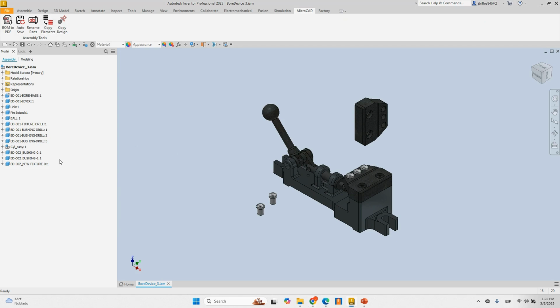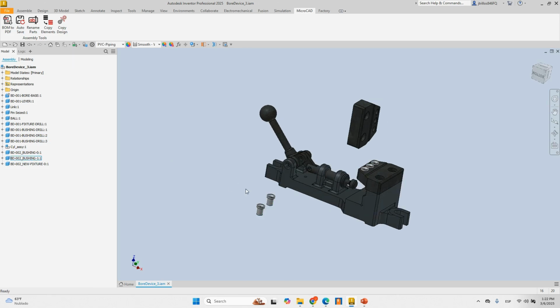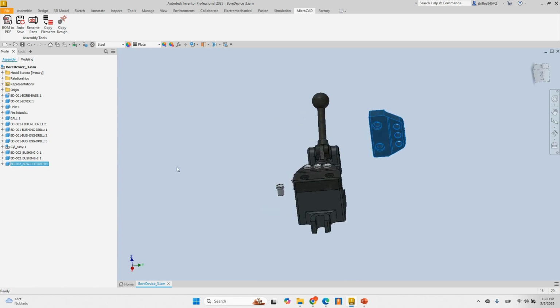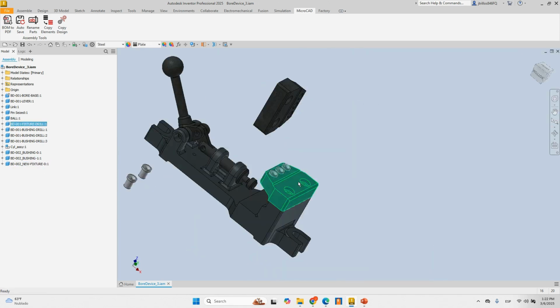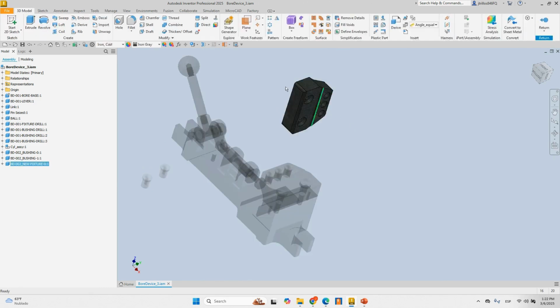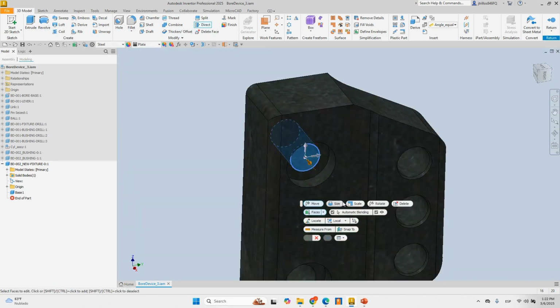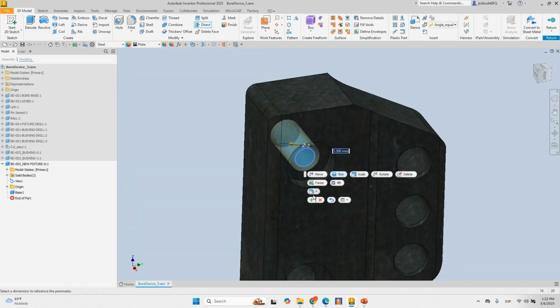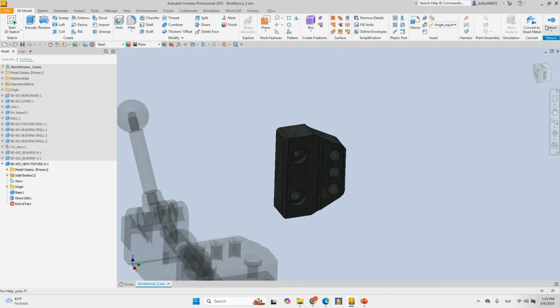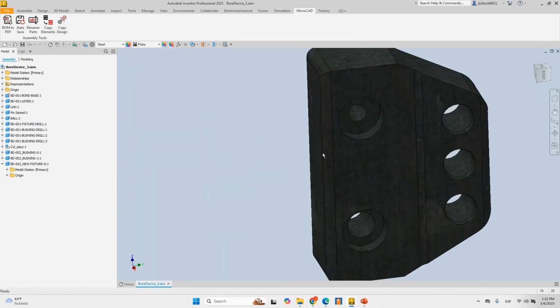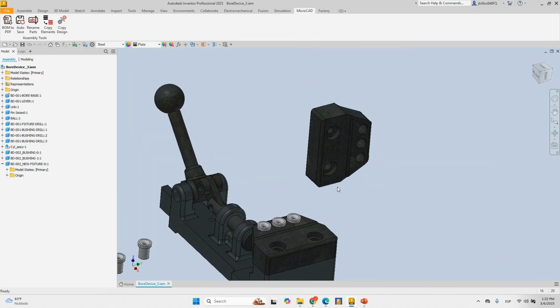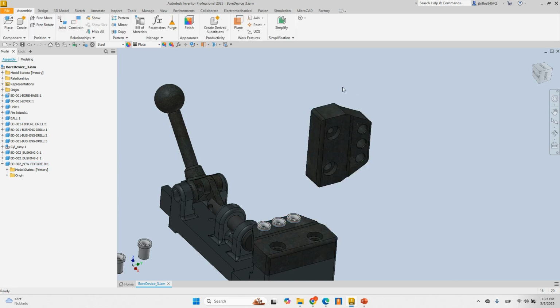Okay. Now, all right. So I got these new files, right? Bushing 0 and bushing 1. And I got this new feature based on this part that I created before. So I can go ahead and modify this one as needed. Say I need something smaller like that, or basically any changes that I need for this new version. Okay, but I can get a head start, and it's gonna be a lot faster than opening the part, saving it with a new name, going into assembly, placing the part, and so on. Okay.